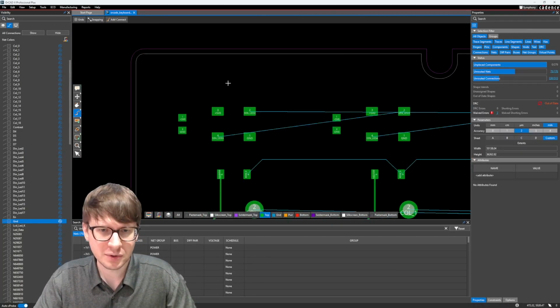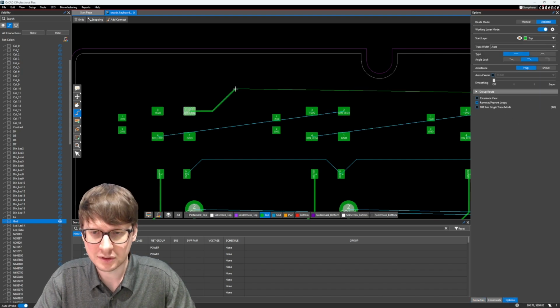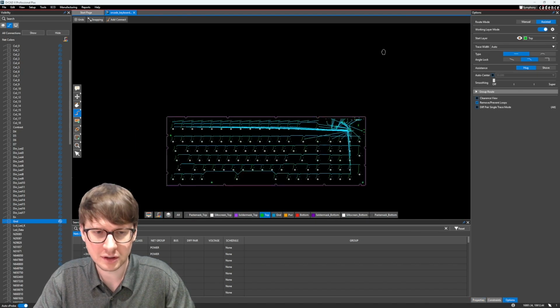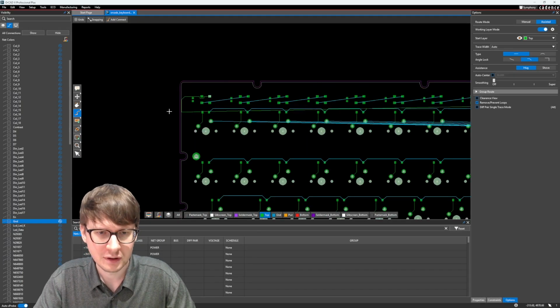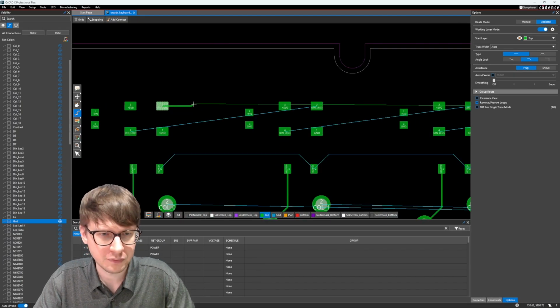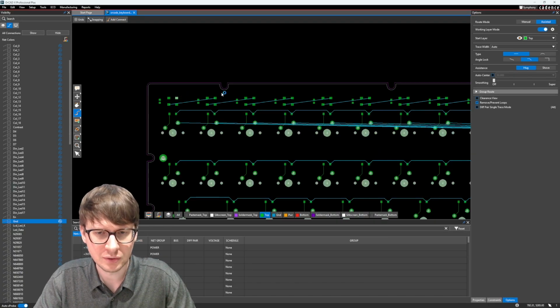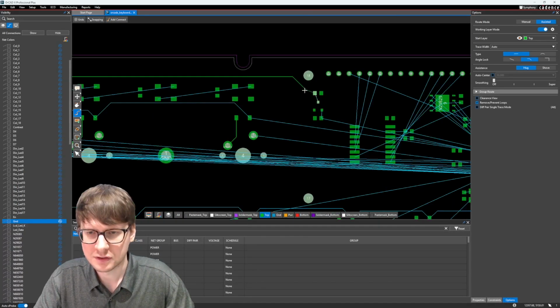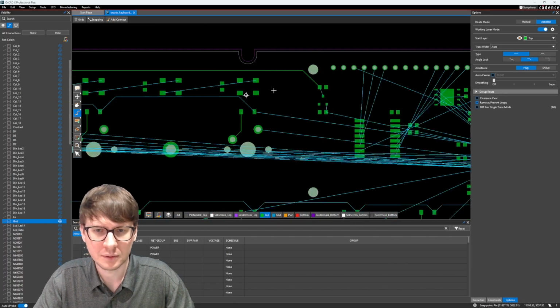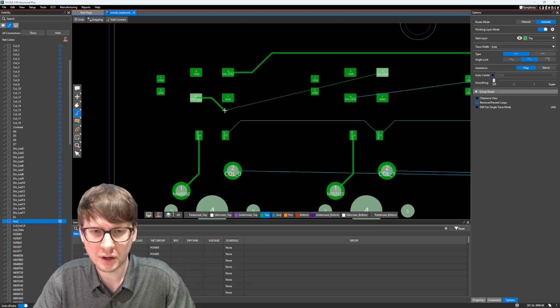So the next thing we're going to do really quickly is just all of these LEDs. Again, these are very simple. The data in of one connects to the data out of another. And let's see, D in LED 2. So this will go all the way to our controller, somewhere over here. And then these should just connect diagonally from one side to the other.